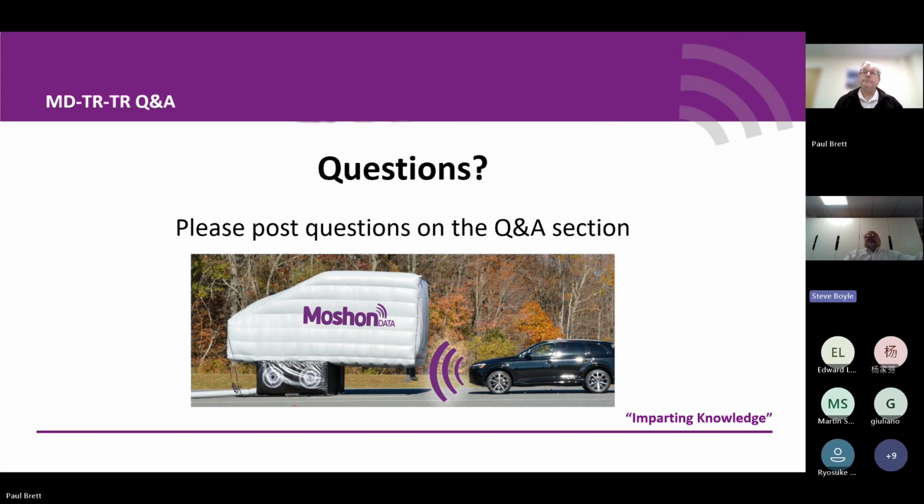Because the stationary object from the rear is one of the hardest things to detect, because these things look like a road sign, and you tend to ignore a road sign, and then you stop one in the middle of the road, it's 4 meters high, looking like a road sign. The only thing it doesn't have written on it is Gothenburg 60 kilometers this way. So that's why the hardest test is the stationary object test, which is what it's designed for.